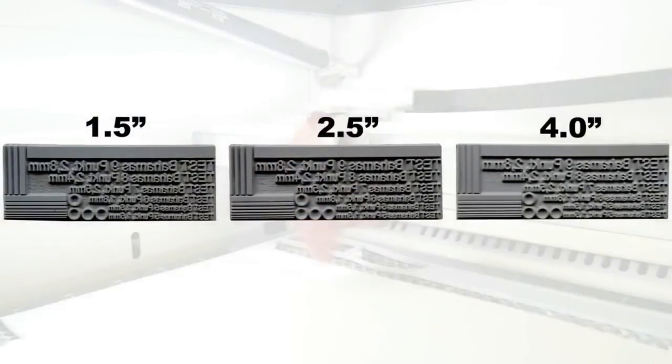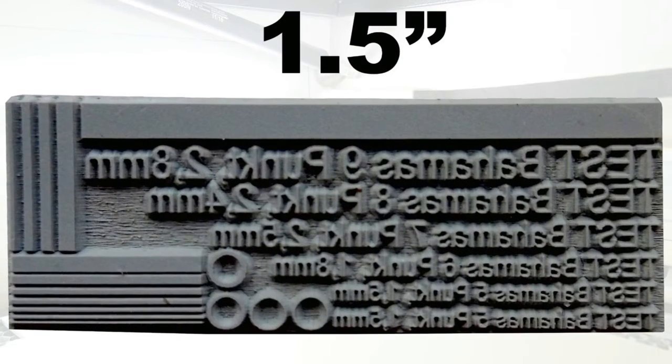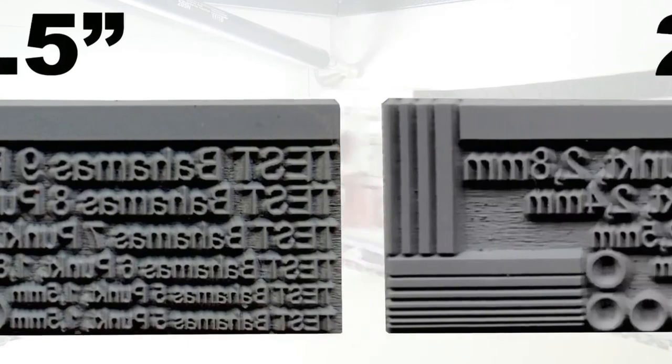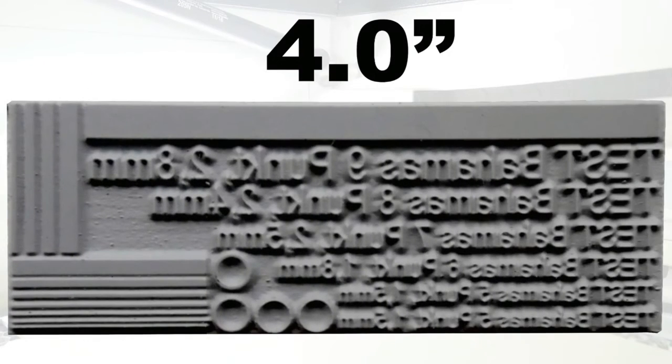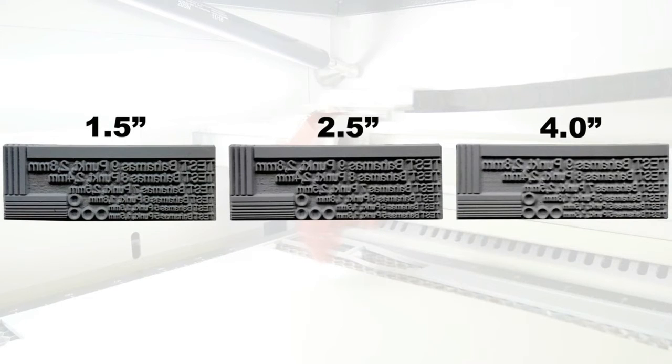Let's do the same test on a piece of rubber. So here we can see the results on 3 pieces of rubber, and as we can see here, the 1.5-inch lens is able to produce the clearest engraving in the areas where we have the smallest details. In contrast to the 4-inch lens test here, it doesn't look very good. It looks a bit bold and undefined. Since we are removing the background and leaving the text, it is difficult to capture the different results due to the shoulders you need around each element when doing a rubber stamp.